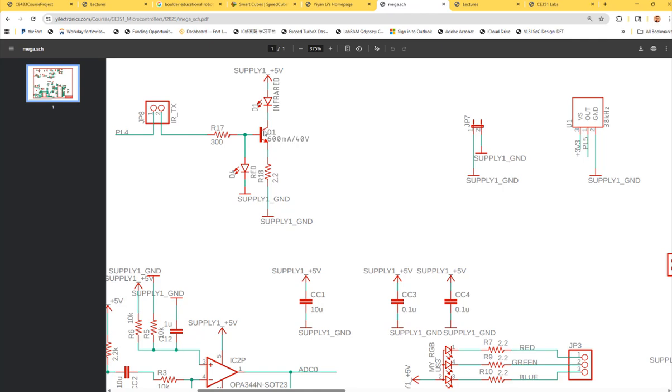Two steps. First, check the soldering of the LED. Reflow the solder at the pad of the LED. And I reflow it, I put on flux, I reflow it, still not working. What's next? The LED is burned. Replace it. Okay? Then replace it with a new LED on this old board. It should work after that. If it's still not working, maybe you can replace the BJT, but it should work, okay?